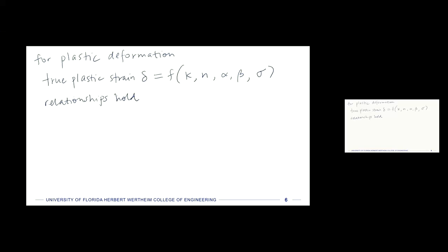And then the approach that we're going to take is we are going to say, let's go back to our stress strain diagram. Right, so when we talked about this initially, we had, let me change that to a sigma. We talked about true stress and strain, not the engineering stress and strain, but true stress and strain, which means instantaneous areas, instantaneous lengths. And the true stress and strain curve doesn't arc back over and lower in stress before failure, right? It sort of goes something like this. All right, so this is where we're going to have to make use of kind of something we assume about this in order to solve this.